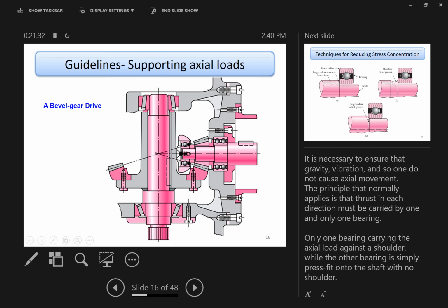And this side of the bearing, you look at it, that's so-called rigidly fixed. You see the bearing here, one side is against the shoulder, and on the other side there's this cover, rigidly pressed against the bearing. So this bearing is rigidly fixed here.